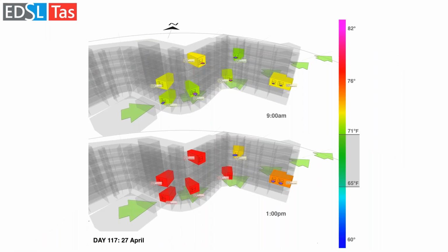And again, taking natural ventilation as a concept of analysis, applying it to the whole model could be useful, but also before doing that, maybe picking a subset of rooms to analyze just different orientations for natural ventilation, to check how it works at different times of day and different times of year. So this is looking at a day in April, 9 a.m. or 1 p.m. In the morning, it actually still maintains comfortable temperatures for these different orientations. But by noon, when the sun's really up, the high exposure, where the annual insolation was very high, is basically too hot.